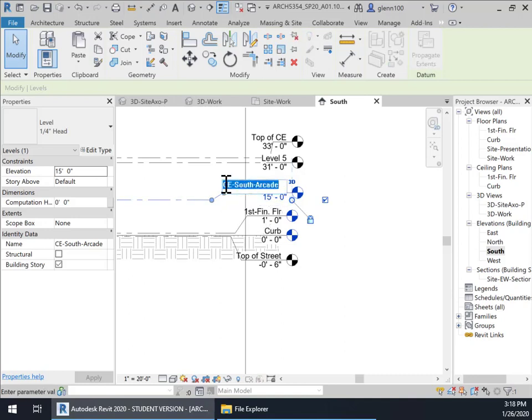So what I'm going to do is come back in, and I could hide this level and keep it if I wanted to, but I don't think I'm going to bother with that. It'll just clutter my whole model up. So I'm going to call this the second finish, and I'll use the same naming convention that I used on the one below it, finished floor. You could put the periods in. You could just use a space to save some length. And so then I'm going to put this up. So 1 foot to 18 feet is going to be 19 feet, from floor to floor.